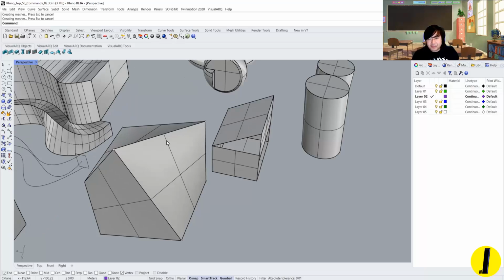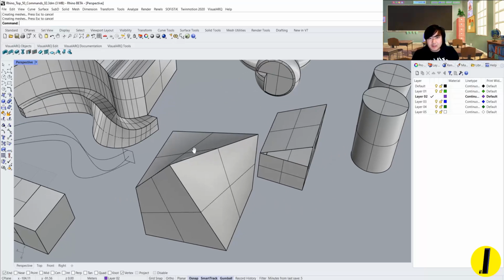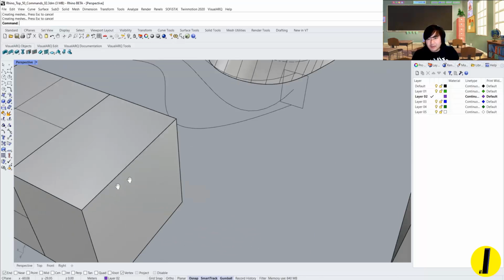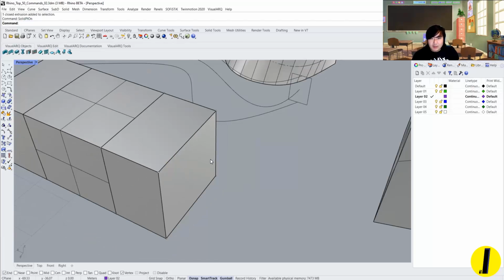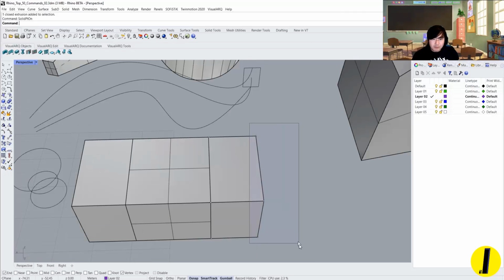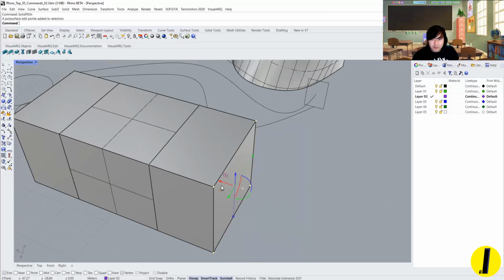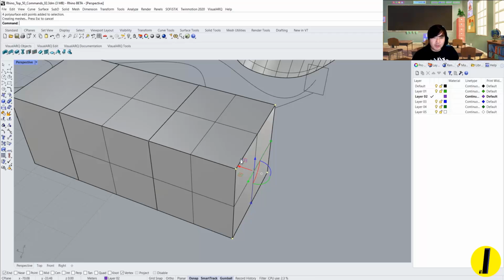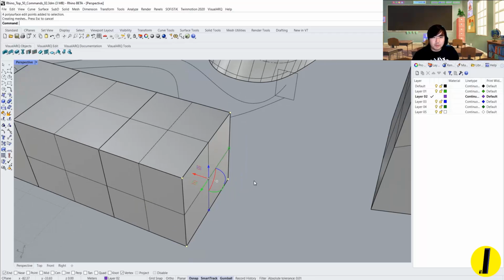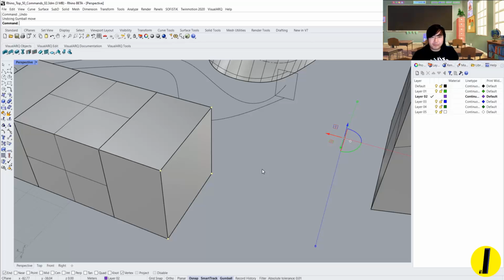So this solid point on command is also very useful. For instance, if I want to move this face, I can select 4 points from here, give -4 meter and hit enter. Because of the 4 points, the whole surface is moved. So let me undo.